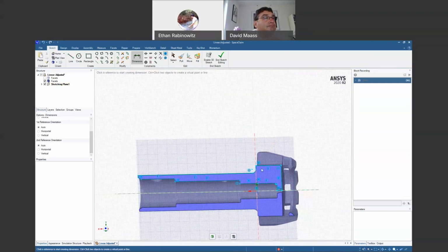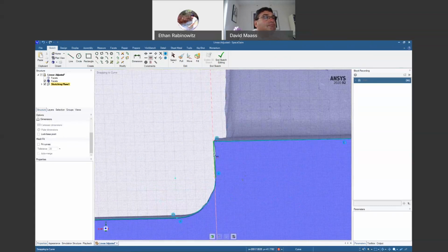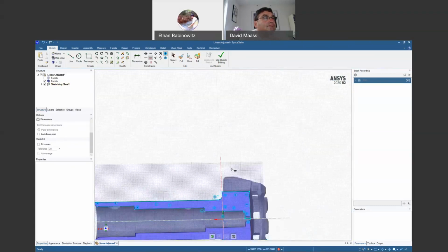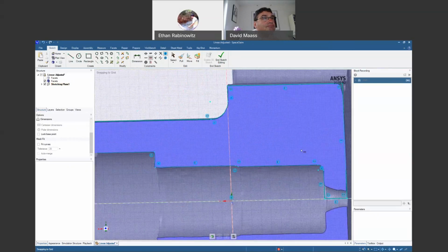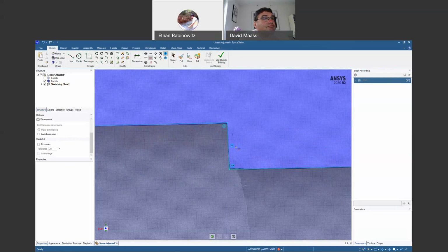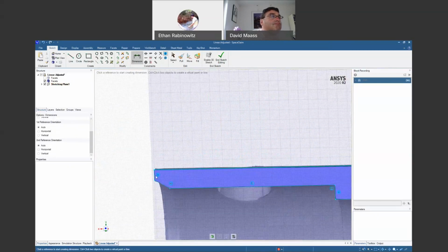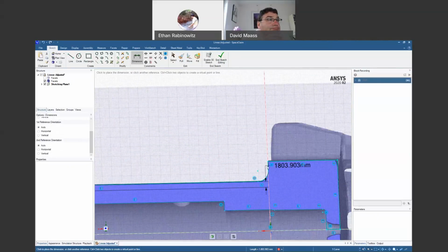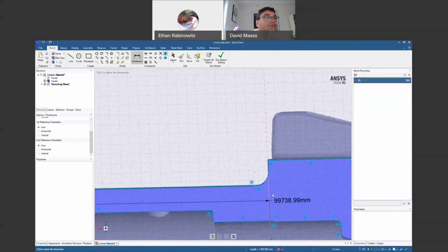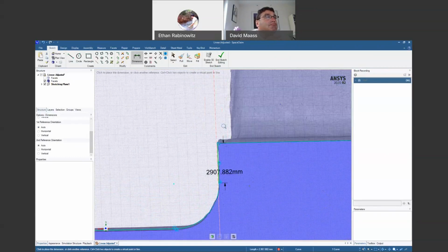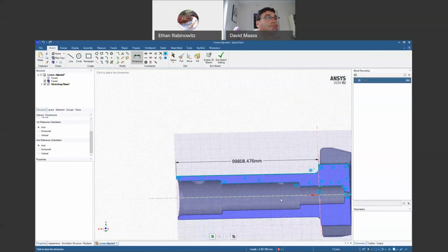Oh, you know what? The sketches that I added, I have not fixed to horizontal, although I thought I sketched them out that way. So let's just verify that one there, and this one here. There. That already has one. That has one. Okay, I think we're good. This will be at an angle, so let's just grab our dimension tool again and go from this line over. Okay, so actually I just clicked on this datum axis, which is not what I want. So let me zoom in a little bit closer, grab that line here, zoom out, zoom in, grab that one. We'll go ahead and dimension that there.